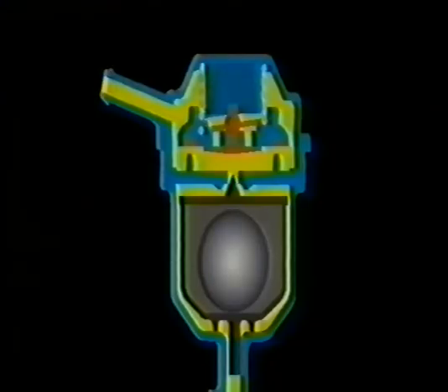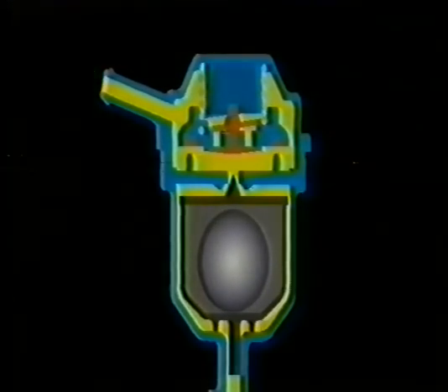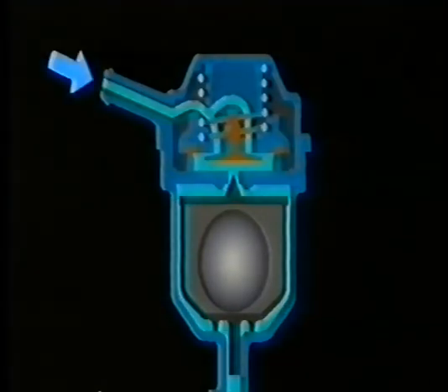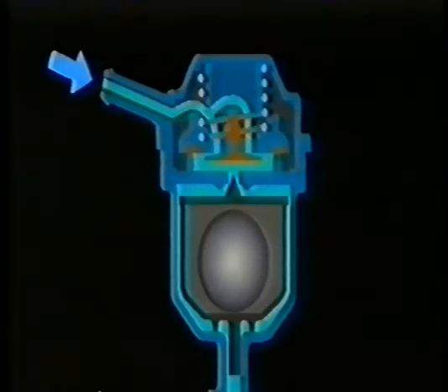The valve works in the same way as the radiator cap fitted to a cooling system. Excess pressure is released to atmosphere by an internal valve lifting off its seat against spring pressure. A second valve allows air to be admitted into the tank as the fuel level and temperature falls.